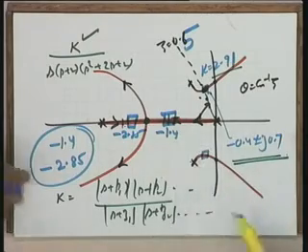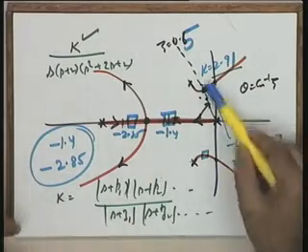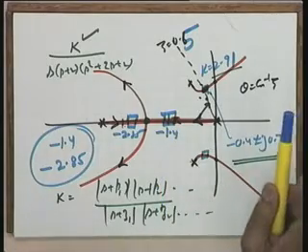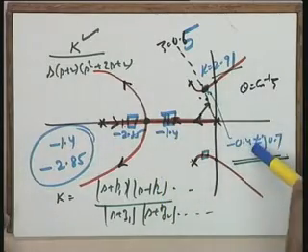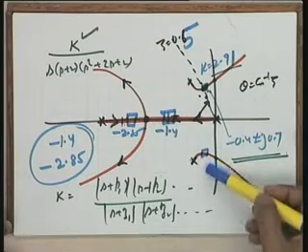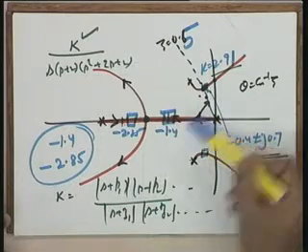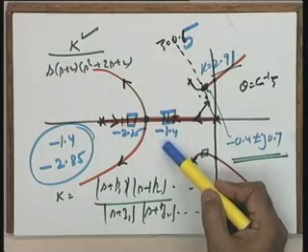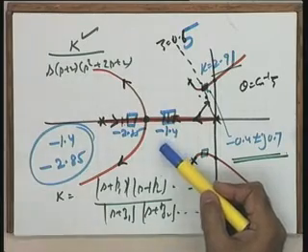So you see that for the closed loop system these are the 4 poles, and you find that your dominance condition is not satisfied, because the real portion of the complex conjugate poles is 0.4 and the other pole is 1.4. It is roughly 3 times away and you want roughly 4 to 5 times away.